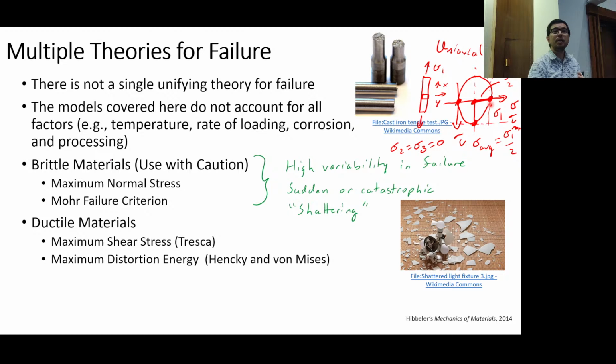Okay, so the Mohr circle is extremely useful for quickly being able to remember what in the world is happening in uniaxial loading and what is the equivalent state of maximum shear stress. Why did I say absolute maximum shear stress, and why am I being casual with saying it's not just the max in-plane shear stress? Well, all three of our principal stresses are on this diagram. We have sigma 1, sigma 2, and sigma 3 right here at 0.